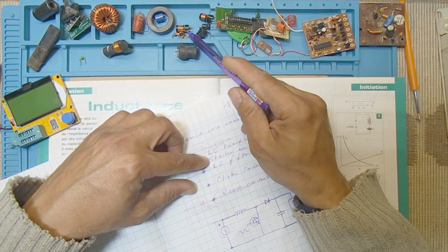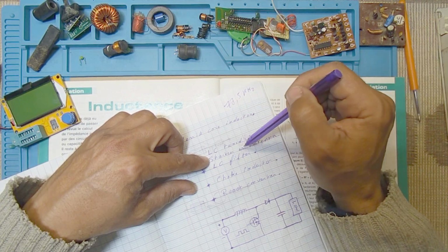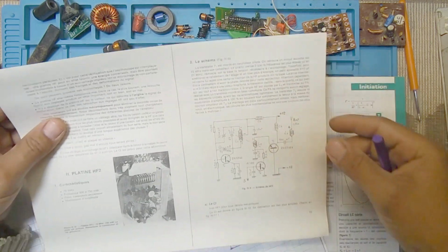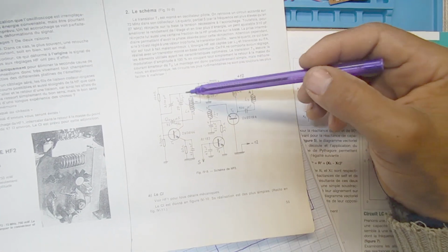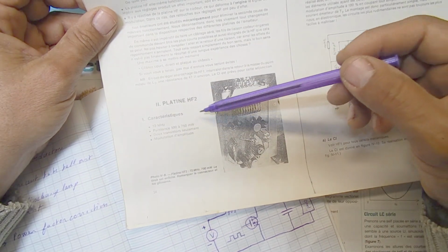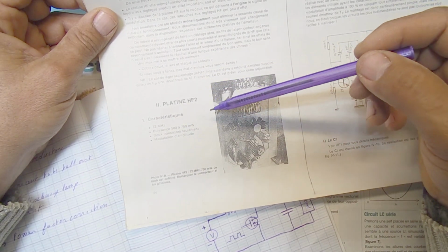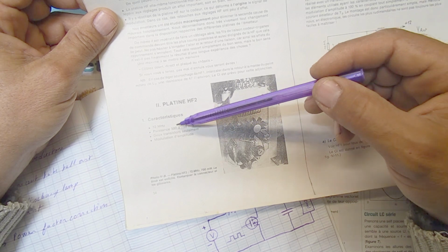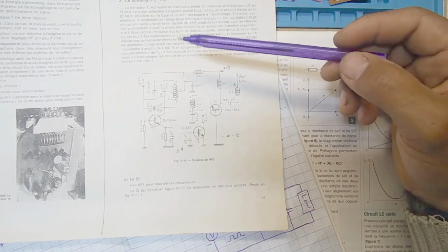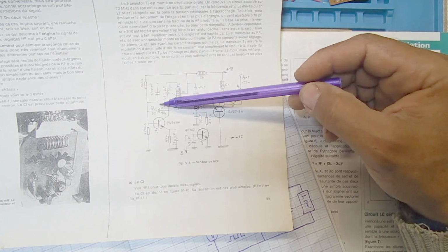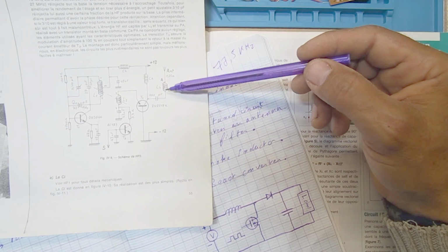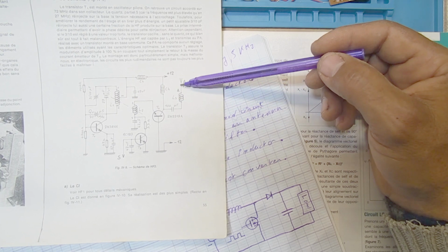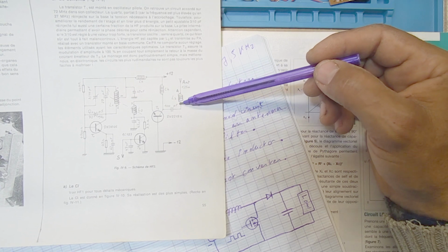We can also use this inductor to shorten an antenna. For example, in this circuit we have a tuned LC circuit. This is the oscillator. This one is a 72 megahertz transmitter for an RC car, for example, a radio controlled car or toy. It has a power of 750 milliwatt. So we find here the LC circuit. This is the quartz oscillator. And here we have this L3. Its function is to shorten the antenna. We can use a small, short antenna with this coil.